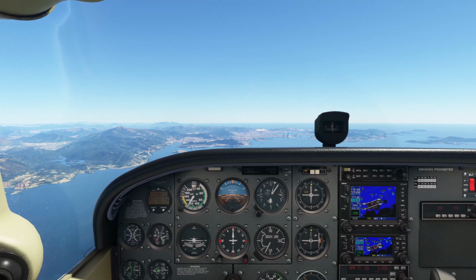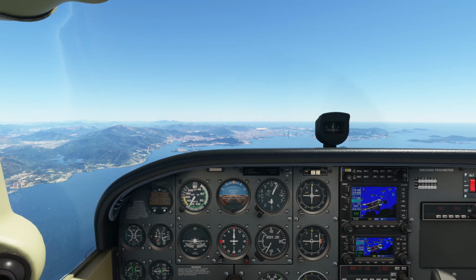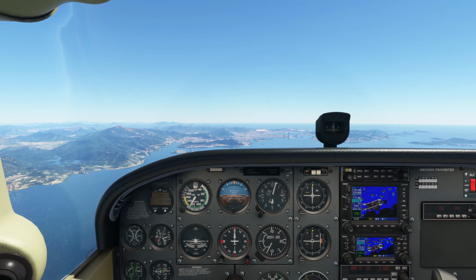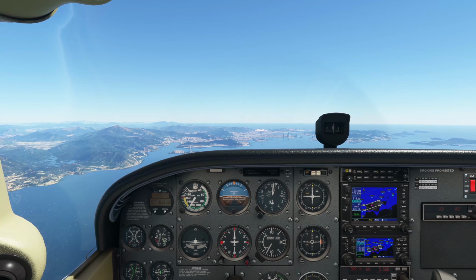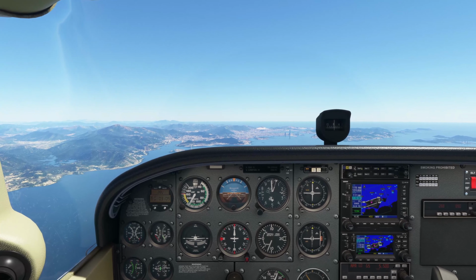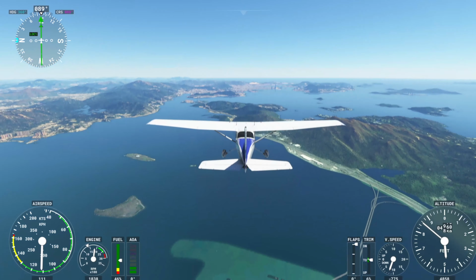Once we are below 1,000 feet, we will disengage the autopilot and fly the final approach by hand. The ILS will not take us directly onto the runway. At the infamous Checkerboard Hill, we will make a turn onto the runway heading.